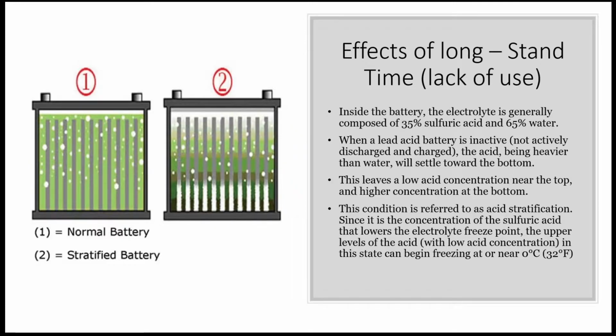You can't charge a frozen battery. If you try to charge a frozen battery, you take a chance of damaging it, one, or blowing it up, two. And it's a very bad thing. So if you're dealing with a frozen battery, you should put it in a room somewhere that can defrost it in the range of at least 50, 60 degrees until the battery comes to temperature. You need to leave it there for probably a good 6 to 12 hours and let that battery completely come to temperature, and then try to charge it or do what you want to do to service it and recover it.